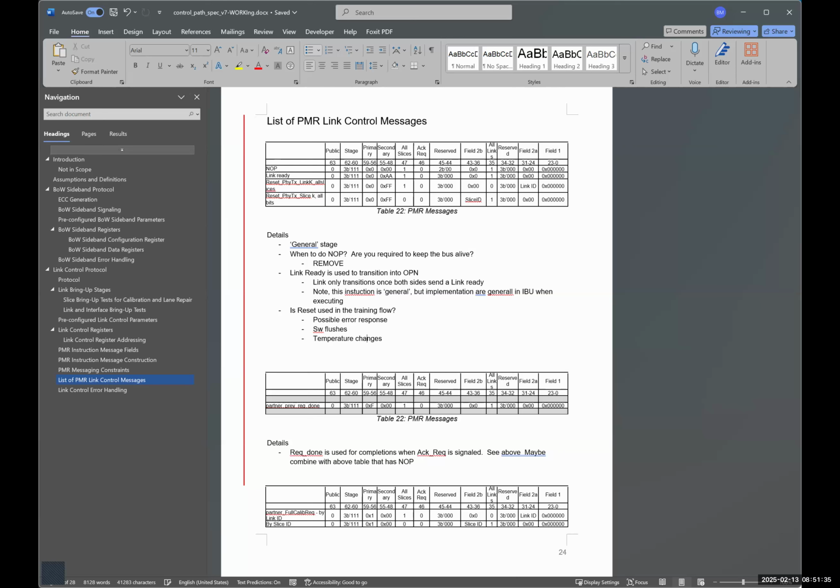They don't necessarily have to send a reset back, because the side that is requesting a reset is already going through the reset, so that side only needs an ACK. I think the only time both sides would be sending the reset is when both sides detect an error at approximately the same time, and both sides' software is requesting a reset. That is probably the only time you would see the reset request go from both directions.